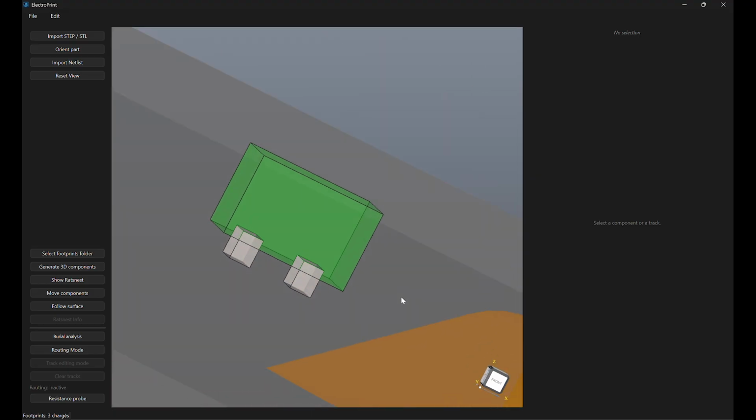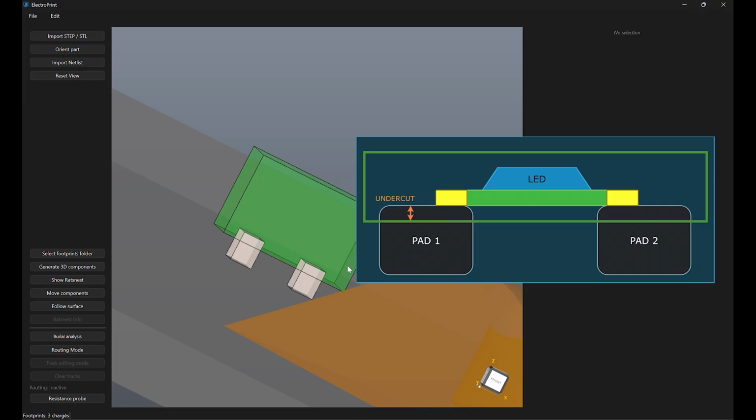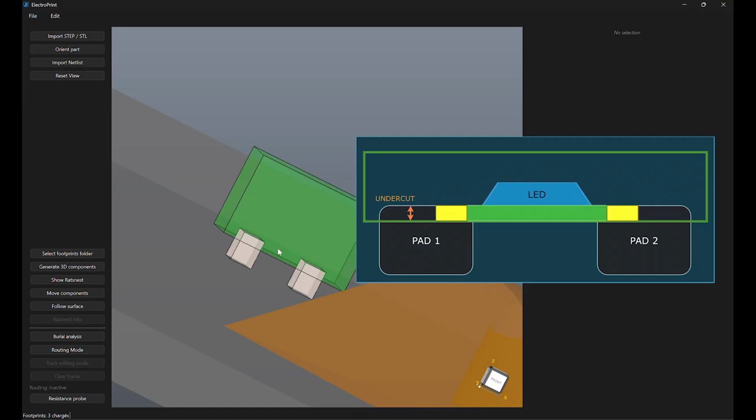The component's pads are vertically extruded, but there is a part that goes inside of the block. It's called undercut. It's very useful during the assembly of the component. When you push the component while heating the pads, you need some space for the component to properly sit on the pads before reaching the bottom of the cavity. It's included to allow a better connection between the component's pads and the 3D printed conductive pads.